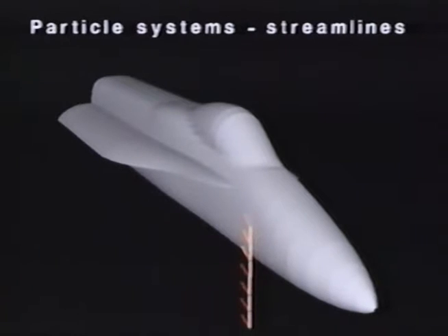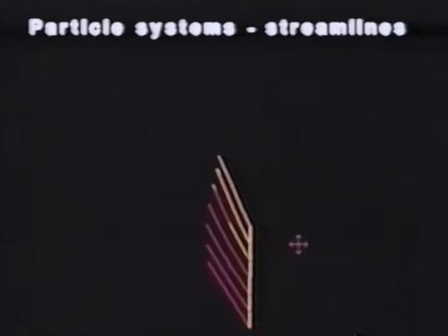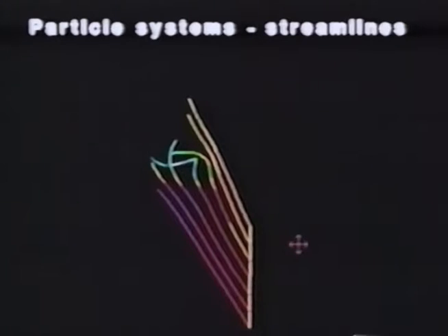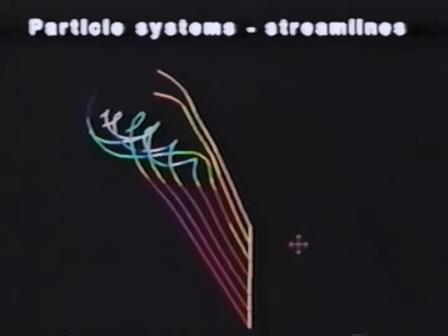With the particles option current, a variety of configuration choices, such as particle count, integration technique, and release mode are available. In this example, we'll choose to launch particles in a packet from a one-dimensional emitter. The particles are leaving streamline trails, which are colored by pressure. A change of display mode removes the fuselage while the particle traces are being calculated. Line width for the traces had been increased for improved visibility. Once the calculation of the traces is complete, the display refreshes to include all currently enabled tools.